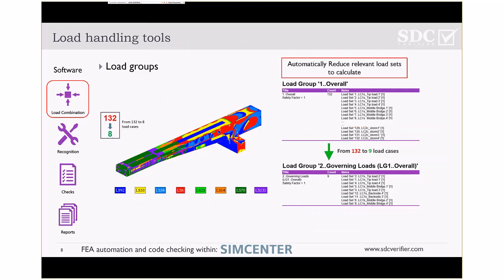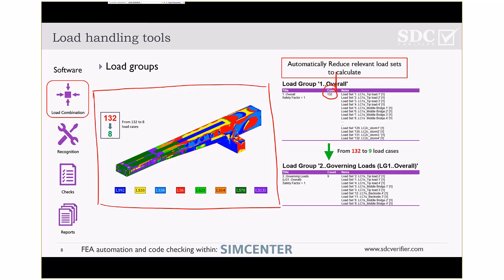Not only can we handle a lot of load cases, it comes together with some nice extra tools as well. In this case we had an example with 132 load cases, and we wanted to figure out, if we have overshoots or if we want to update and change our design, which load cases give the maximum stress at which position. In this plot we can get a plot for any criteria: maximum stress, maximum buckling factor, maximum fatigue result, all these kinds of things.